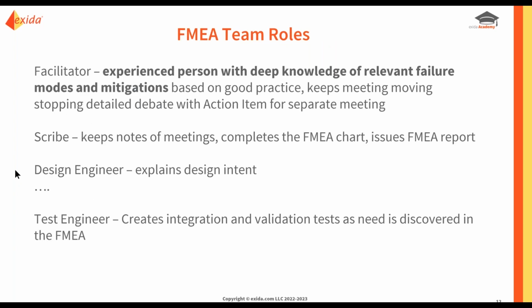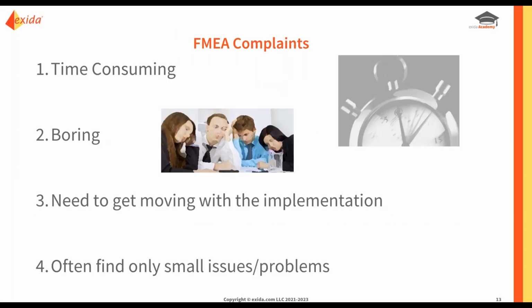Keep in mind, even the minimum FMEA team, which is a facilitator, a scribe, a design engineer, as minimum, and in many cases, a test engineer who can document the integration and validation tests during the FMEA as the need becomes obvious, which it does in an FMEA. Now, I know the concept of defining integration tests and validation tests during an FMEA is not common, but I cannot imagine a better time and place to do it in order to achieve that other important goal, minimizing engineering hours.